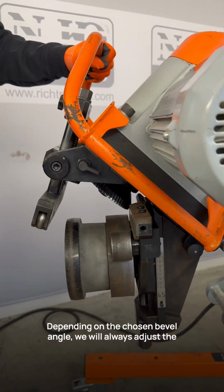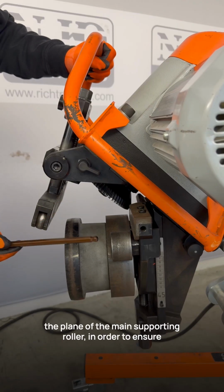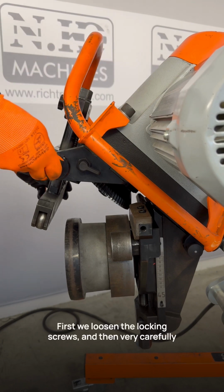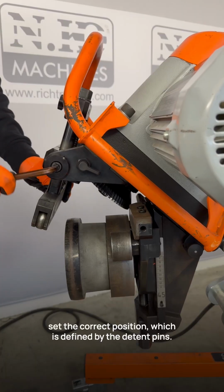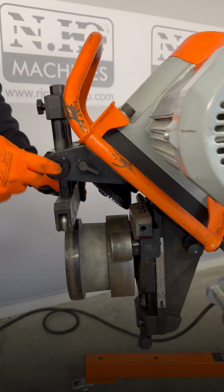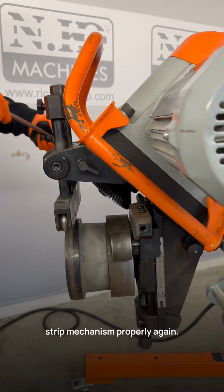Depending on the chosen bevel angle, we will always adjust the position of the upper pressing strip so that it remains perpendicular to the plane of the main supporting roller, in order to ensure proper alignment in all cases. First, we loosen the locking screws, and then very carefully set the correct position, which is defined by the detent pins. Careful! Don't forget to tighten the securing bolts of the upper clamp strip mechanism properly again.